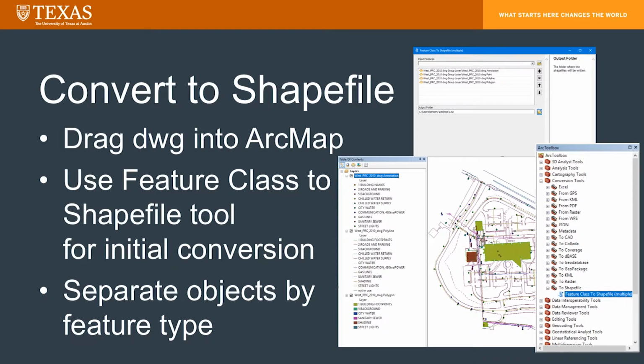After you have run this tool, and at this stage of the game, there's a bunch of different ways that you can do this, actually. I'm not sure how we did it in the beginning, but I find it easier to just take the DWG file and do one export and create one shapefile. Well, actually, it's going to be 3 shapefiles: the point, the polygon, and the polyline feature class. And then I have a basis to start querying out and separating out all the different features.